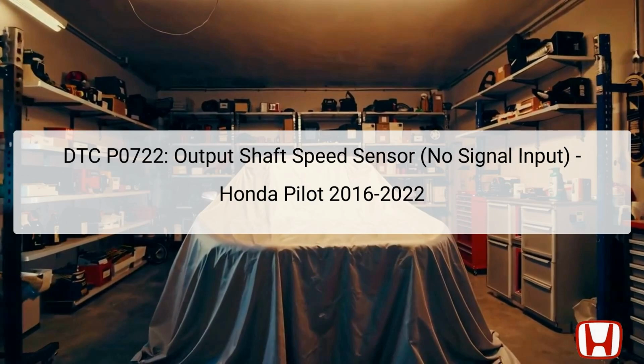This presentation addresses the Diagnostic Trouble Code, DTC P0722, which pertains to the output shaft countershaft speed sensor, indicating a no-signal input error. This issue primarily involves the electrical circuitry associated with the sensor, rather than any mechanical faults in the vehicle's transmission. The Honda Pilot, manufactured between 2016 and 2022, is equipped with advanced systems where the proper functioning of the speed sensor is crucial for optimal driving performance.